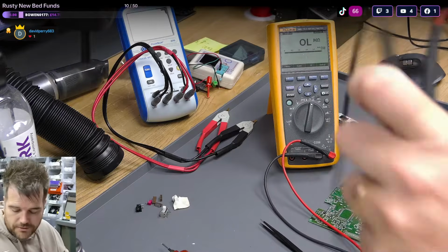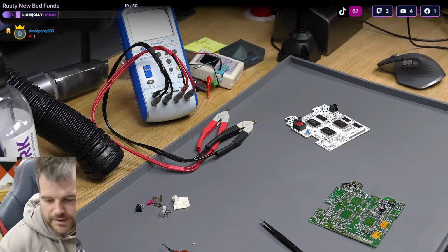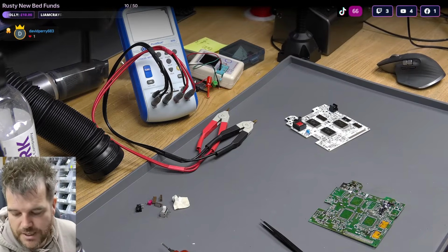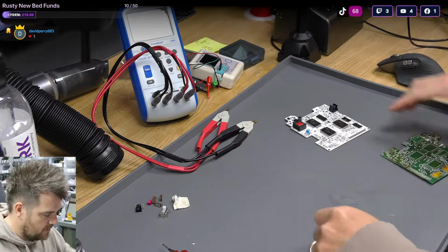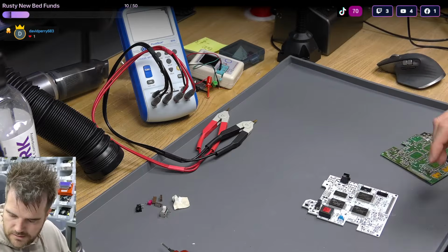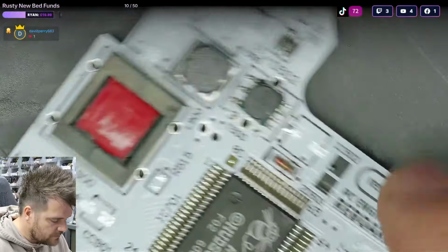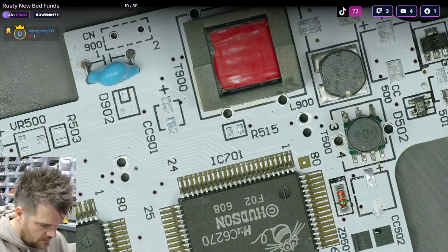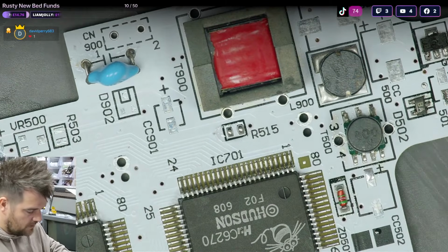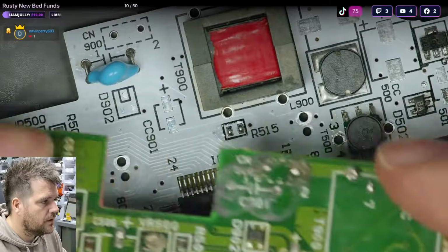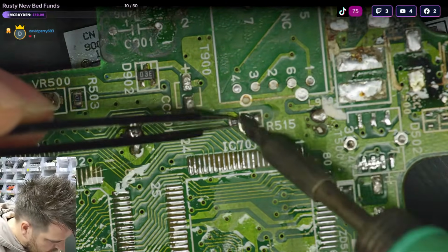So you can rely on the readings and be confident and just swap them, but I want to be very accurate on this. I want to take my time and make sure I've 100% seen every component is what it says. So let's pre-tin this board now, ready for accepting the new resistor. Solder on there. I don't even need to hot air it off because we've already lifted it off, so just take it off like that.